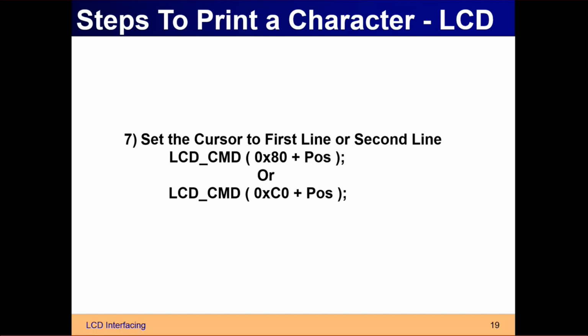If you are writing data to the corresponding address in the character generation RAM, the data from that address onwards will be displayed on the first line. From the other address onwards, it will be displayed on the second line.